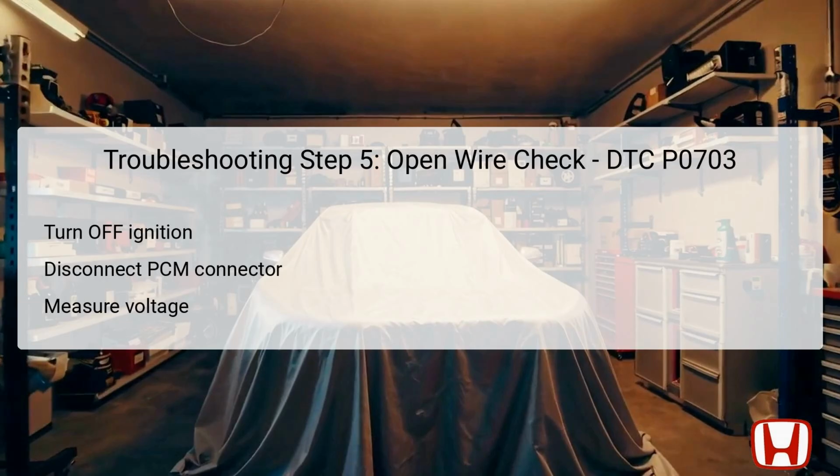Following this, disconnect the PCM connector A51P. Then, using jumper wires, connect terminals A and B within the brake pedal position switch 4P connector. After setting up your connections, turn the vehicle back to the on mode. It's essential to measure the voltage between test points 1 and 2 during this step.